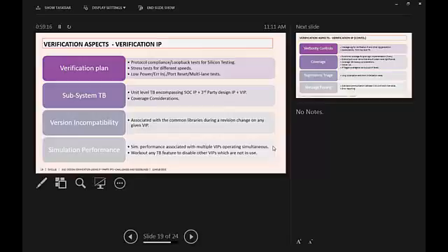They would have verified each separately: the SATA VIP separately compiled and verified, and the PCIe separately, and then they put the package together and send it to you. So when you try to compile both, you may face some version incompatibility problems. Once you find the issues, you may need to get the next version release.